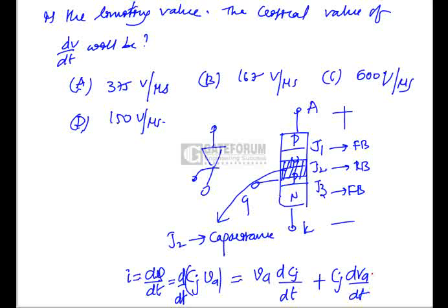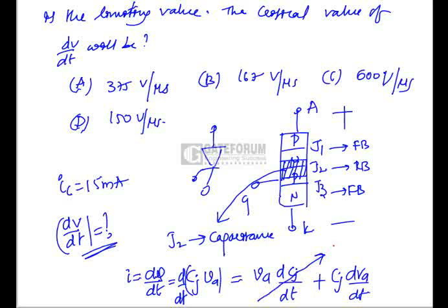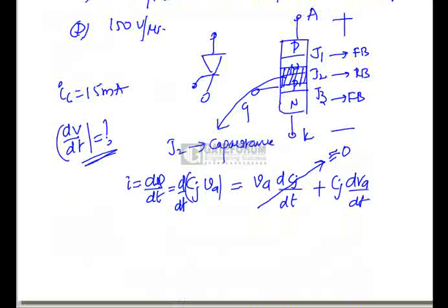Okay, now the charging current to turn on thyristor, he has given as charging current IC is equal to 15 milliamperes, and we have to find critical dV by dt. Okay, that is dV by dt is equal to how much? If you see here, the change in junction capacitance with respect to time is almost 0. We will take it as 0. Now charging current IC is equal to Cj times of dV by dt. Okay, this is nothing but V is equal to anode voltage Va.